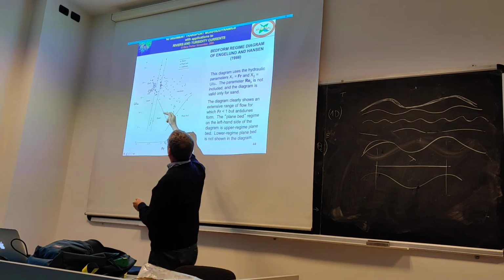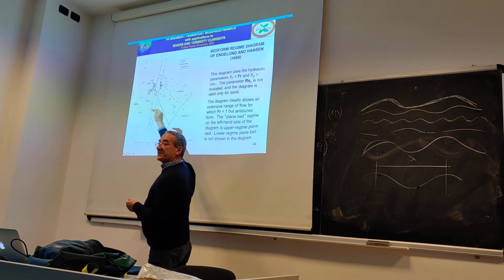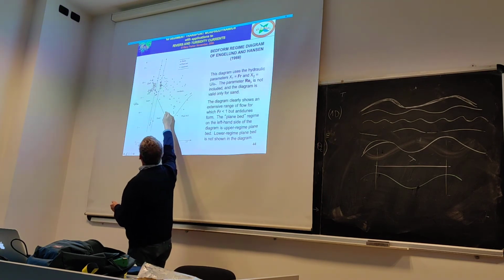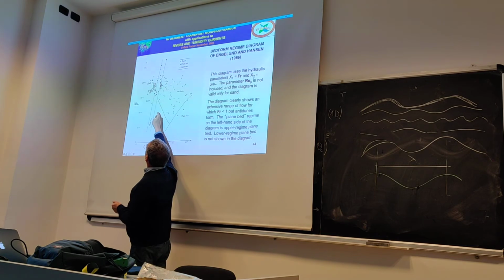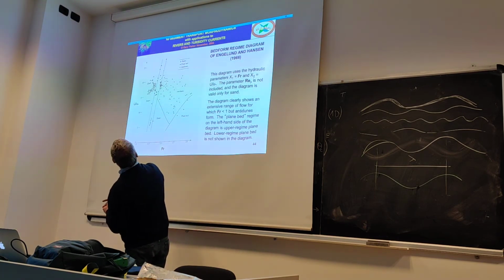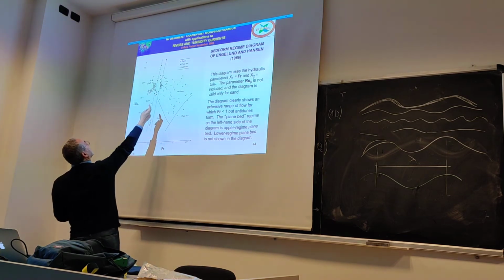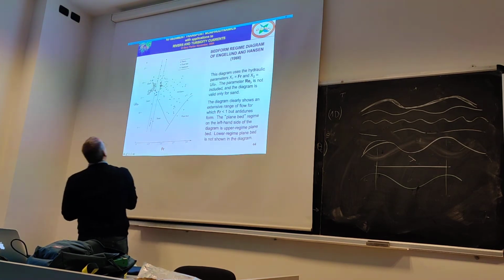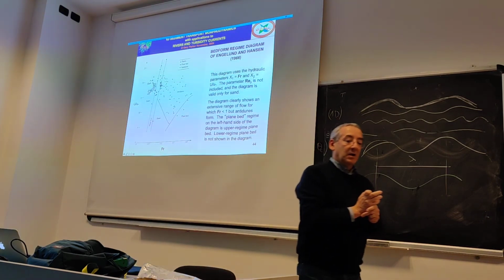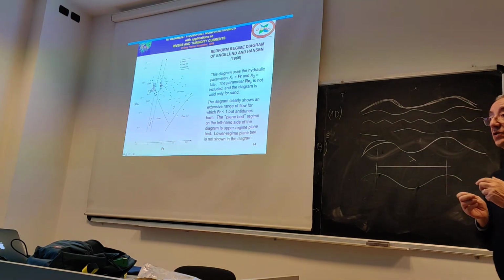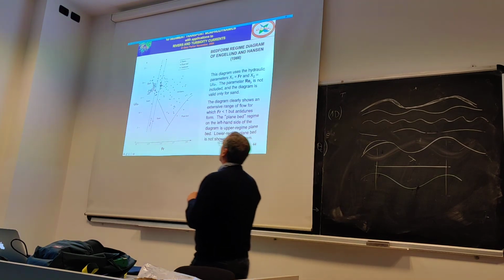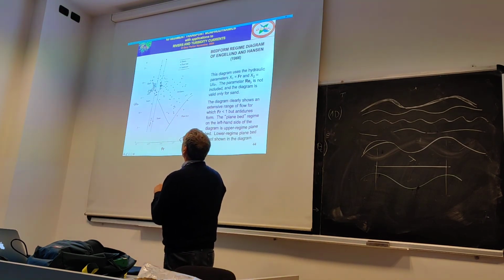So if you lower the Froude number or you lower the Shields stress, you have the formation of dunes here. These are all dunes. Between anti-dunes and dunes you have a region in which you have a plane bed solution. This is what is called the upper regime plane bed, upper plane bed regime.